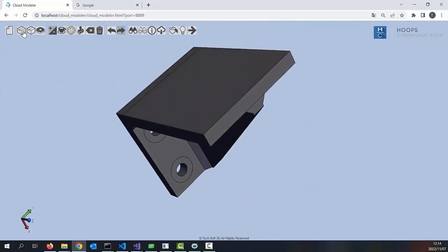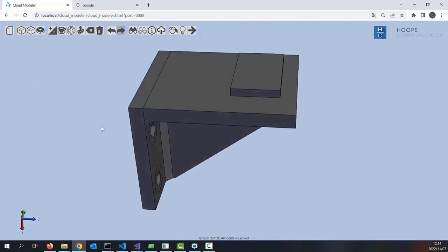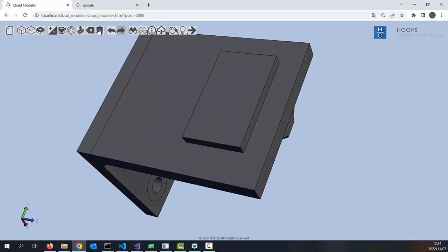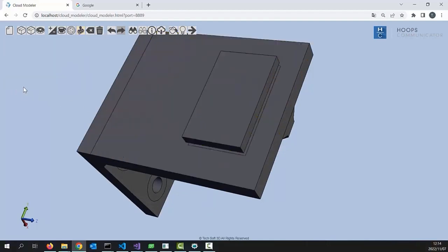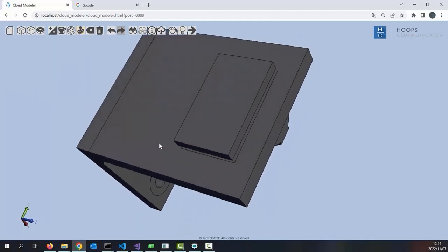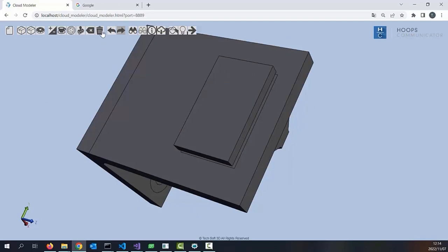We will utilize Parasolid once again to create a block that represents a rubber pad, which is designed to mate against this part. We then use this rubber pad to project and define the region that a load will be applied to during simulation. Now that this boundary condition has been defined, we can delete this temporary geometry.